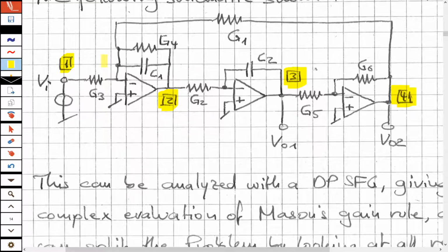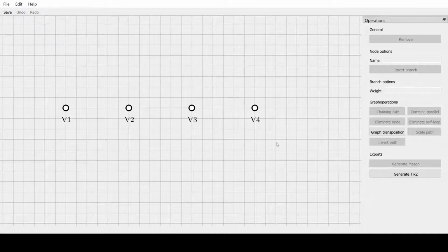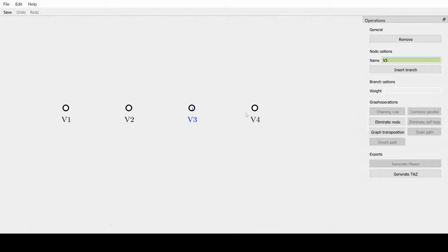This here is the simple one, isn't it? It has 2 resistors, a G5 and a G6. Now let's make it even simpler. Let me call this G5 and this is also G5. So let's make it the same resistor. Now according to the formula I just saw below, this is minus G5 by G5, which is -1. So the only thing that circuit is doing is amplify the voltage by -1. So I jump over to my graph and insert here the -1.